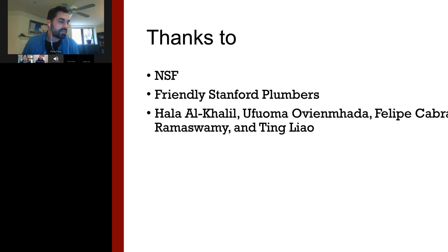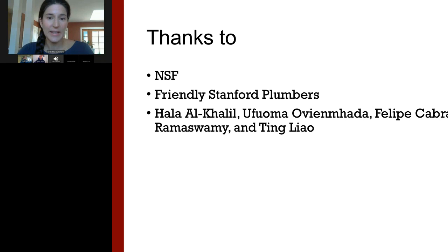Jessica Atwater from Clear Result says, telepathic faucet, very cool. Did the research include how the dishwasher's water usage affected how the water heater was cycling/reheating? So it was an inline water heater, and so it provided a continuous stream of water at a continuous temperature as people turned it off and on. This brings up a very interesting point, which was that the inline water heater isn't instant for the first person in the experiment. It takes a little bit of time. And so we got into this situation where people didn't know if the faucet wasn't working or if it was taking time to heat up. That's something to think about when you go to a full smart faucet. There'll be a moment of hesitation until people get used to the system where they don't know if the faucet has served them the wrong temperature or if the instant water heater is just taking a second to heat up, if this exact implementation was used.